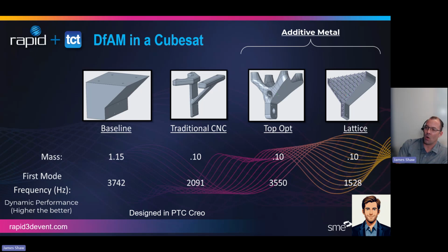Now, the other goal that we have is to maximize what we call the resonant frequency, or the frequency at which this structure will vibrate, were it to withstand some sort of vibration and shock. For these brackets, anything that gets launched, the harshest environment structurally that it's going to experience is leaving our atmosphere, right? We've got, I don't know, tens of Gs, let's say. We're at thousands and thousands of miles an hour. We've got all kinds of vibrations coming from the rocket.